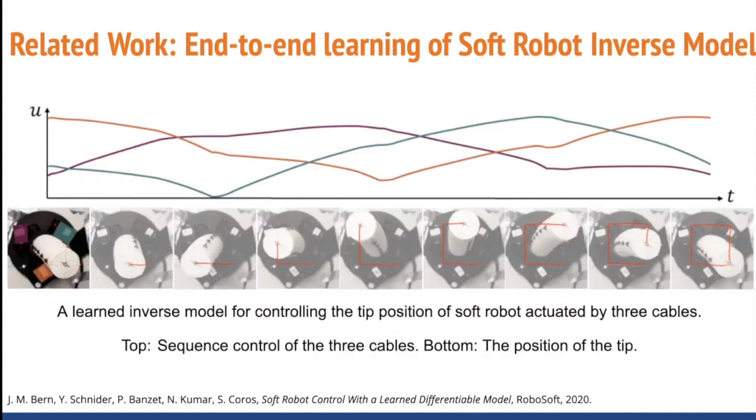We propose to solve this problem using an approach based on data extracted from the simulation. Instead of directly learning the inverse model linking effector position to actuation effort as in previous works, we learn small-scale matrices that capture the mechanical behavior of the soft robot. The learned compact representation is not reserved to a single application, as these matrices could be used for different design and control applications.